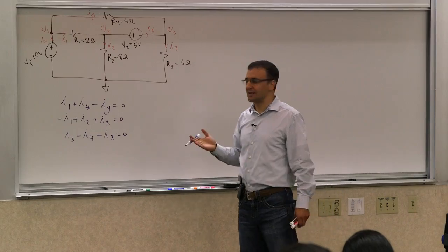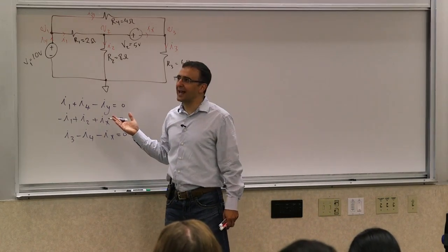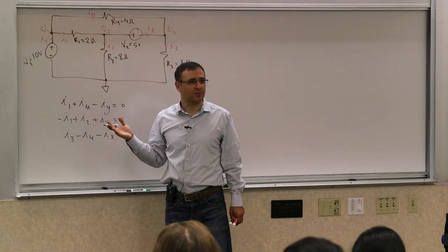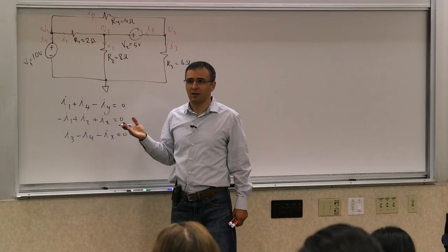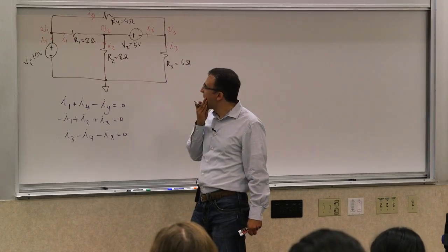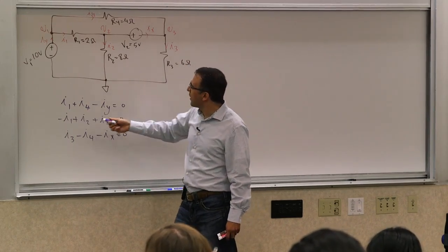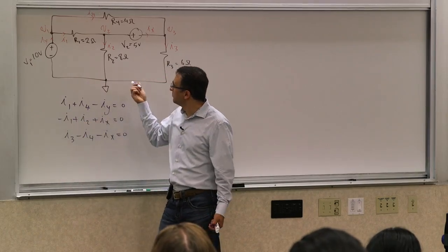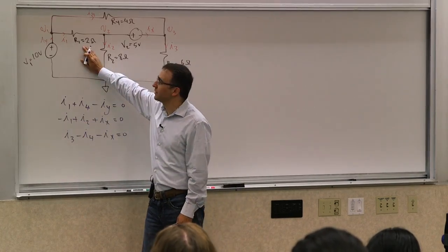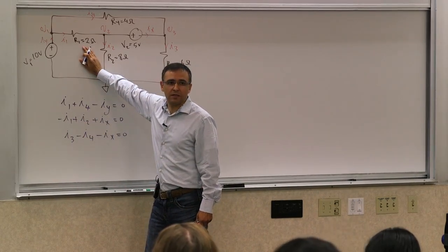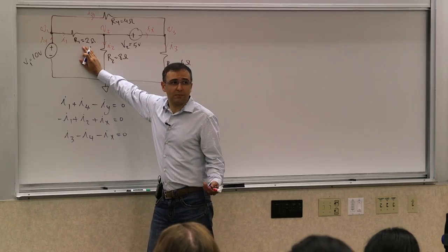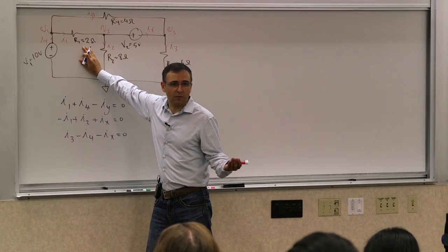So I can still write them in this form, but nodal analysis requires us to write this in terms of the node voltages, right? Some of these, like I1 and I2 and I3 and I4, I have no problem defining them. What is I1 in terms of node voltages? It's V1 divided by R1, or G1 times V1.